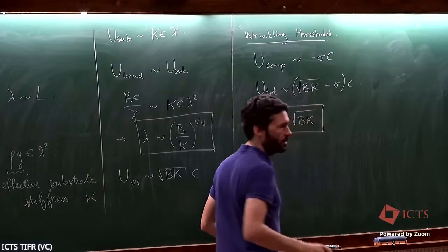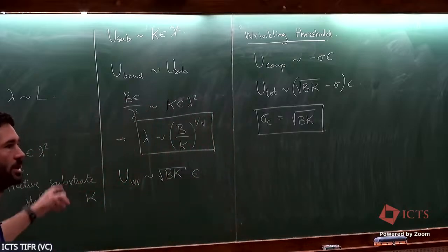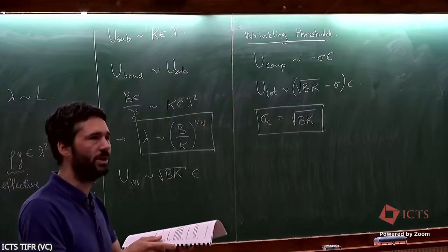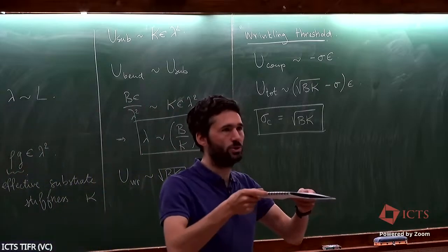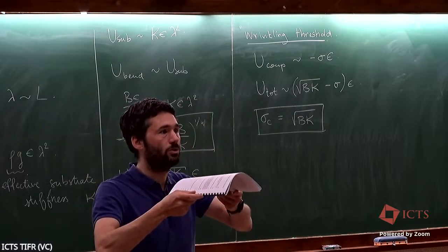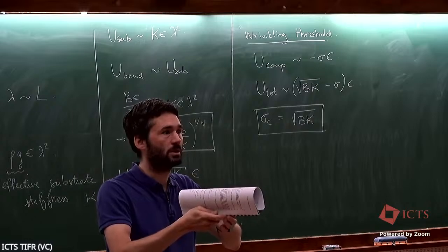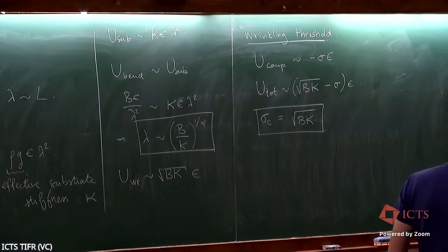And you do not know how it stops because this is linear in epsilon. So it never stops. And actually with Euler buckling, it's not easy because Euler buckling is subcritical, meaning that once you hit the threshold, then if you work at constant force, you go to a complete collapse. But if you do it at imposed displacement, of course, it will stop at some point. Epsilon is imposed.